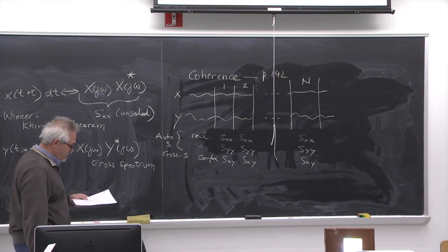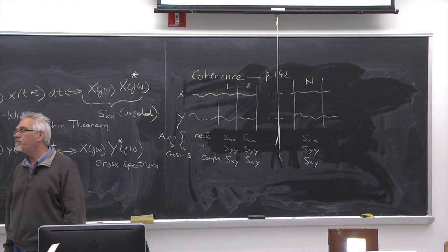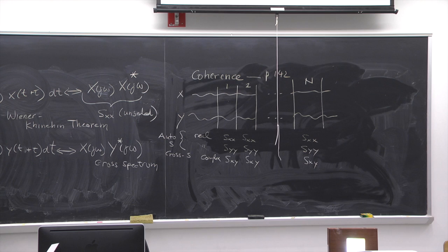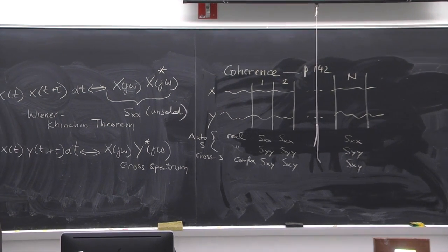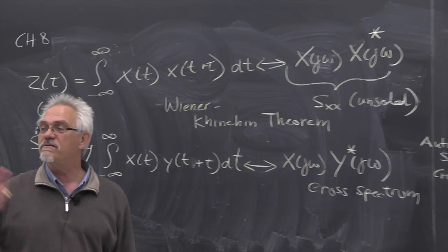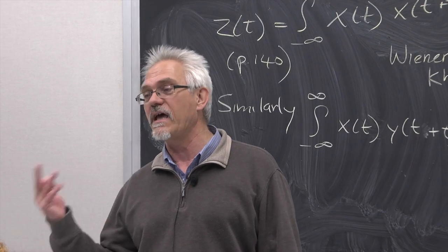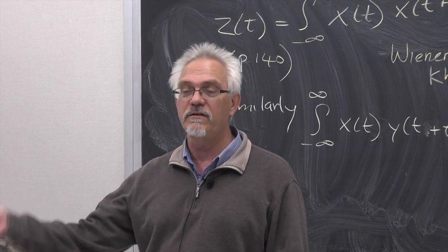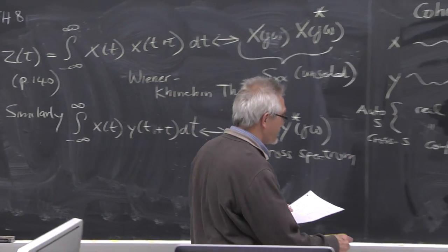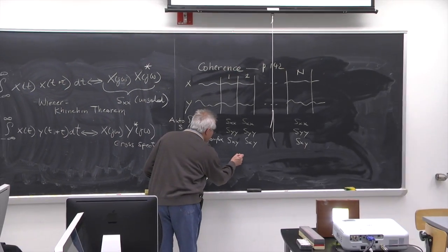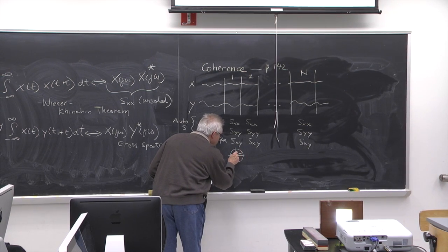And the other thing I can do is, and you will see that this is the whole purpose of the whole exercise, since Sxy is a complex number, I'm going to determine what the phase is of that complex number, which is basically the inverse tangent of the imaginary divided by the real. So for every Sxy, I'm going to just look at what the phase is.